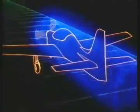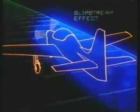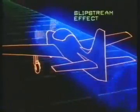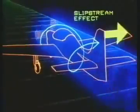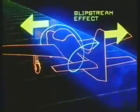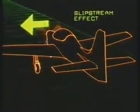The second cause of swing during the takeoff run is produced by the propeller's spiraling slipstream and the resultant asymmetric airflow over the fin and rudder. This generates an aerodynamic force which tends to drive the fin to starboard and the nose to port. There are two more causes of swing during the takeoff run, but these only affect aircraft with a tail wheel.